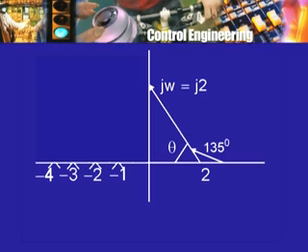But by making these computations, one can get some idea as to whether there is likely to be a point which lies on the root locus. How do the computations go? They go as follows. I first sum all the angles made at the zeros. So here is this point j2, here is the 0 at 2. So I draw this vector going from the 0 to this point, and I have to calculate the angle here.